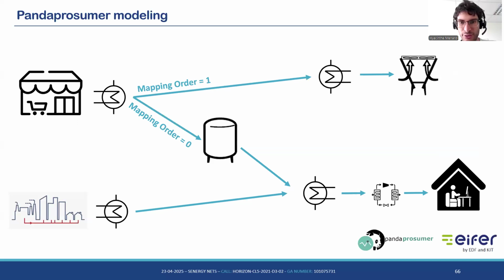And then I will include the dry coolers. The dry coolers I use in the case where there is some extra heat that we cannot supply to the demand or to the storage. So if the demand is already met and the storage is already full, only in this case we want to use the dry coolers. In this case, the heat will be lost in the atmosphere, consuming some electrical power too. So we want to do this only in the last case, if we cannot store the energy anymore in the storage.